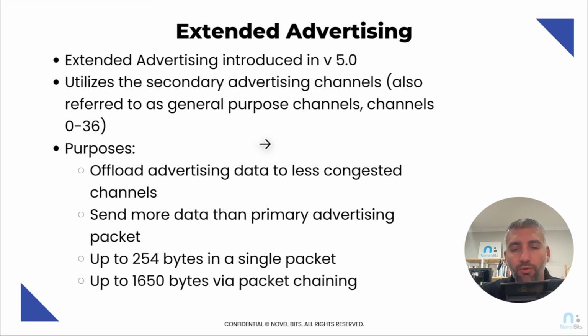So they were only used for connections and during connections between two devices. These are now renamed to be called the general purpose channels. Now, these are channels 0 to 36. Again, if you recall from the first video in the series, we covered that the legacy advertising uses 37, 38, and 39. Well, with extended, it allows you to go beyond that.